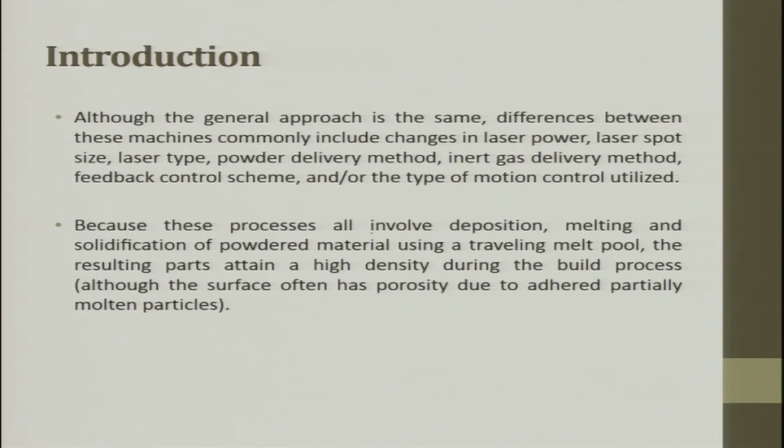Because these processes all involve deposition, melting and solidification of powder material using a traveling melt pool. Deposition, melting, traveling melt pool. That means to say it is not a pool at one point, the pool keeps traveling. As and when the laser keeps moving, it is trying to melt powder and it is going to take it along. With the traveling melt pool, the resulting path attains a high density because all the metal powders are now melted. So, it will all be in a pool form. So, it will have high density during the building process and porosity will be reduced.